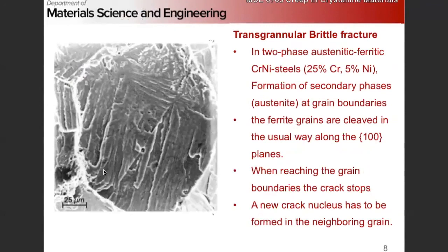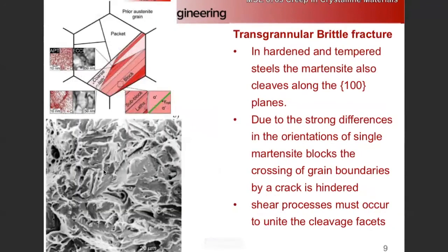Right? How on earth would you get austenite? Austenite is typically the higher-temperature phase, and when you quench, you typically get allotriomorphic ferrite. Right? You get grain boundary ferrite, not grain boundary austenite. Right? But in these systems, you can because of the decomposition from the delta iron reaction. Transgranular, yeah, sorry, I thought we were changing for a second, but this is still transgranular.